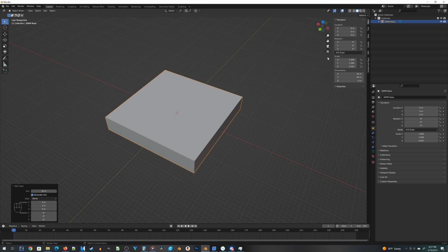It's important to note that 3D printers are not perfectly accurate. They're very close, but within, say, a millimeter or so. Therefore, what I find is that when you're cutting out a hole inside an object for 3D printing, that hole has got to be a little bit bigger than the actual size it needs to be. So even though we may want to cut out about a 25 millimeter square out of this base, because of 3D printing, it's got to be bigger than that. Exactly how much bigger really depends on your setup, and there may be some trial and error here for your printing setup.